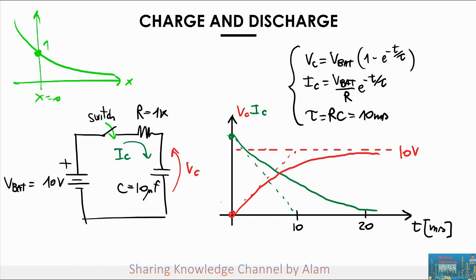Let's now move on to the voltage waveform represented by this equation. Again, to be able to draw or to recognize that the waveform is correct, we just have to individuate the three main points of the exponential curve, which are the starting point, the ending point, and the time constant. Let's start analyzing the waveform to see if it represents correctly the behavior of the voltage of the capacitor in the circuit. The starting point for the voltage was given by the problem itself, and that is something that you always need for a capacitor.